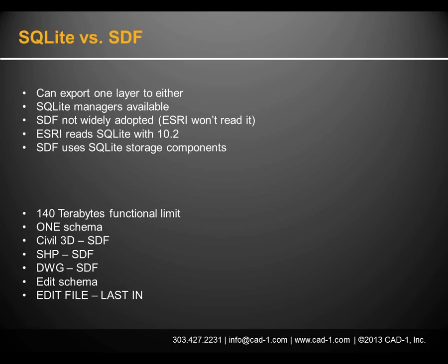If two people are editing the file at the same time, the program will not stop you or warn you. Okay, everybody listening to that one? If you've got one SDF file and two people are doing edits to it, whoever saves last wins. So if I make an edit and save it, and Matisse is over here next to me, and he makes an edit to the same object while I'm working and saves it, his wins. And I never know it until I actually refresh my layer and go, hey, what the? That's not what I did. So you need real good file management, real good practices and workflows for that.